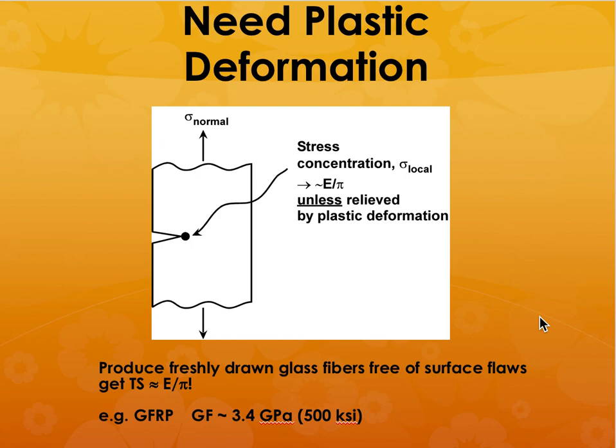What is 5 to 10 microns? How much do you think is the diameter of your hair? Your hair is about 100 microns or about 0.1 millimeters. So a glass fiber or a carbon fiber is of the order of 5 to 10 microns. Carbon fibers are even smaller than that. It can be anywhere from 3 to 5 microns.